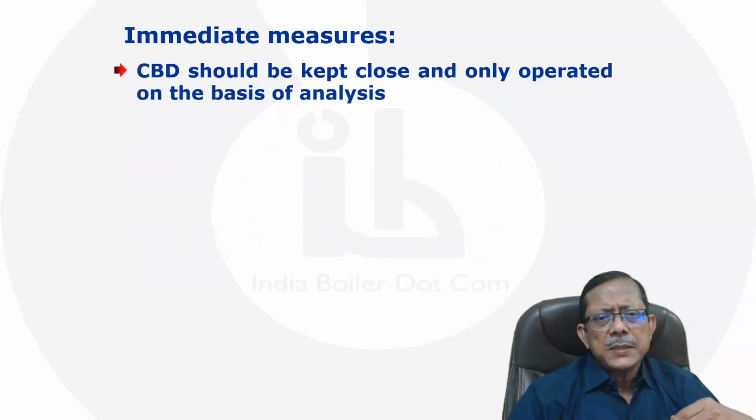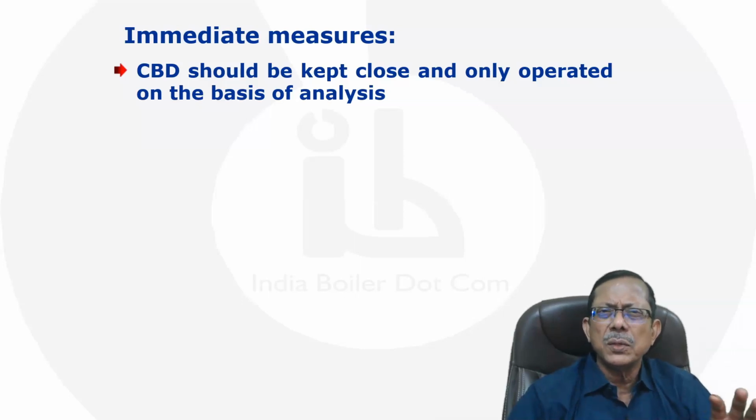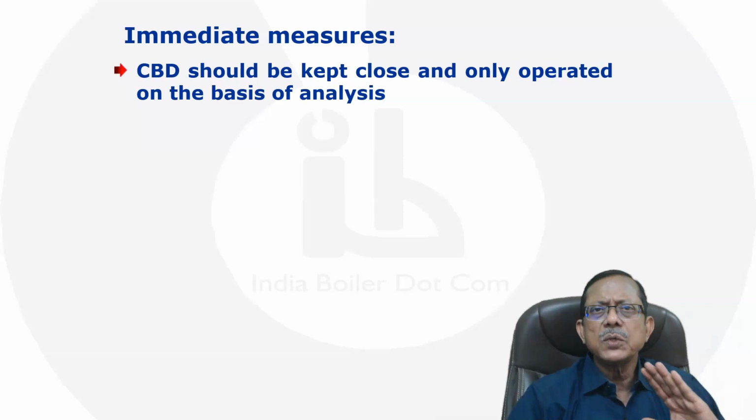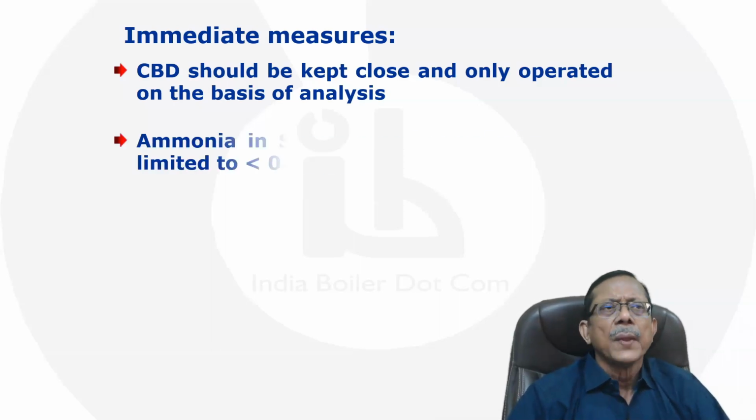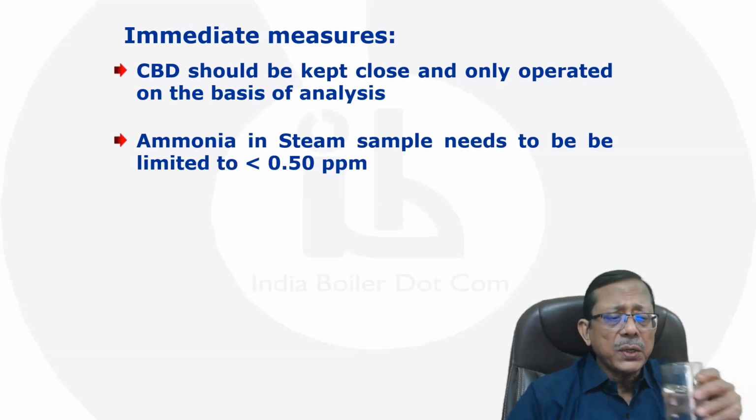Then they were keeping the CBD open, as I told you, and that is always going to make it very difficult to maintain the water chemistry, because you are adding chemical and then you are continuously removing it, right? So the chemical balance will be very difficult. So I asked them not to do that, to stop the continuous blowdown practice, because they were keeping it at least a crack open all the time. So I asked them to stop the CBD and carry out the blowdown as and when required based on the analysis.